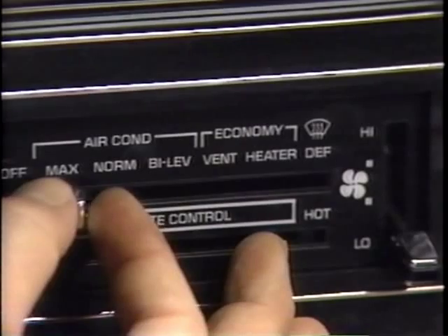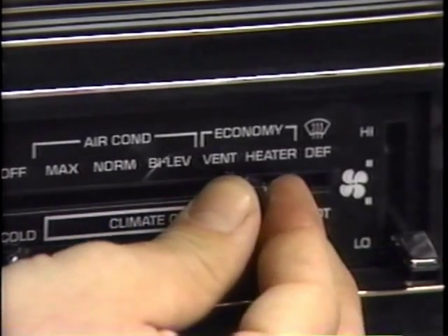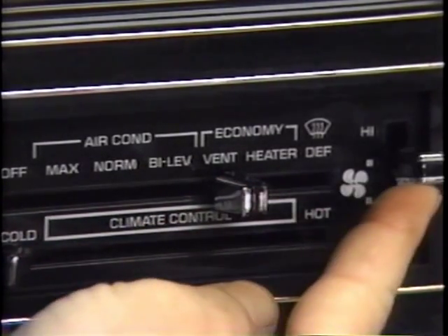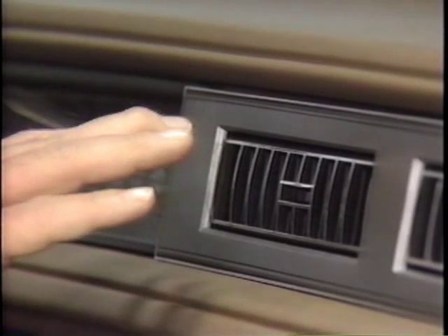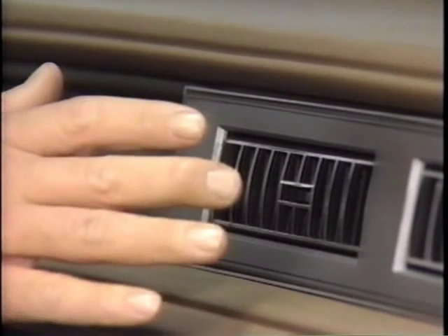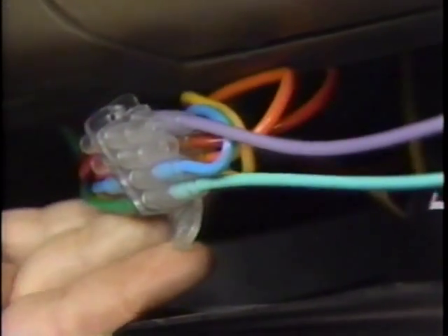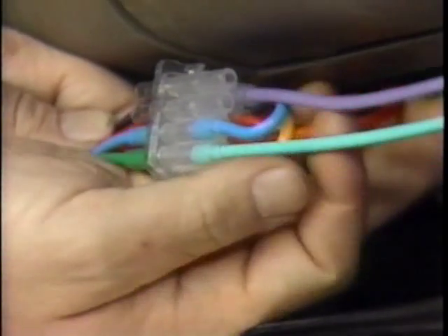Simple logic can reduce your diagnostic time when trying to pinpoint the source of an actuator problem. For example, if air fails to flow from the panel outlets with the manual system in the vent mode, you can be fairly certain that the problem is not with the cable-actuated temperature control.